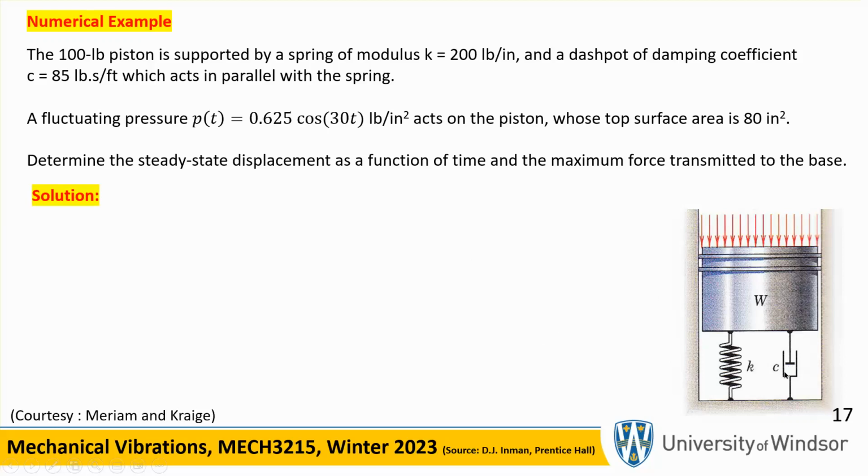This damper is really not there. It's the friction with the walls that is allowing us to replace that friction with some kind of a hypothetical, man-made damper, a human-made damper. Okay. All right. But anyway, we want to find a steady state response, and also at the end, how much force is transmitted to the base. Base meaning your engine, basically, the rest of your engine.